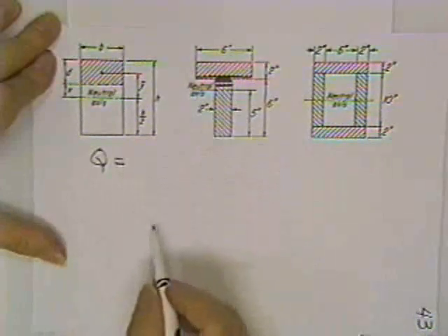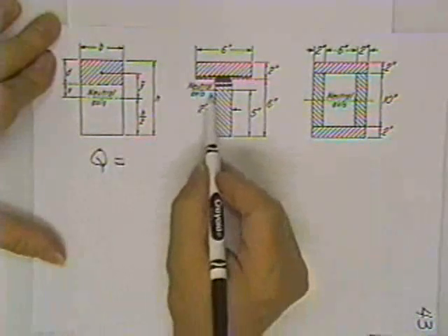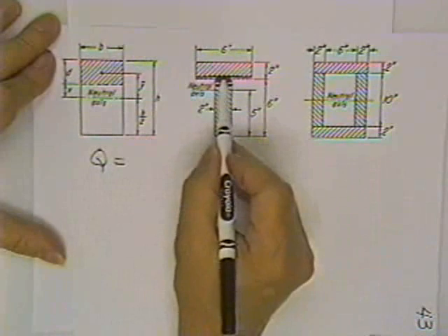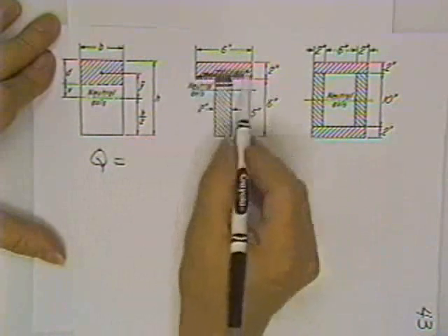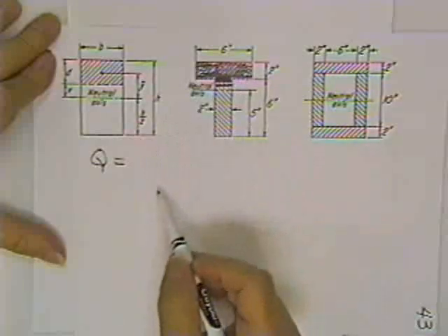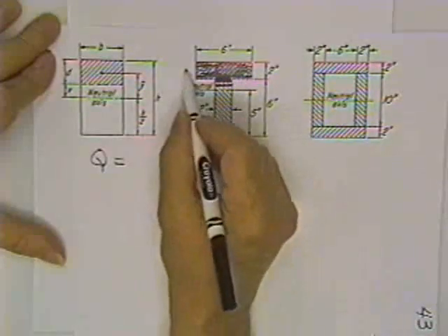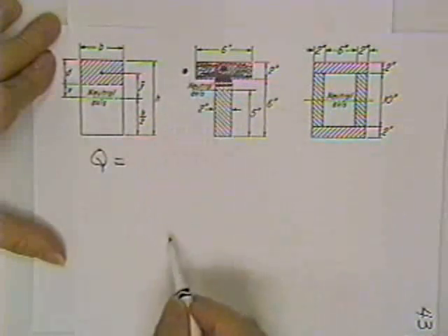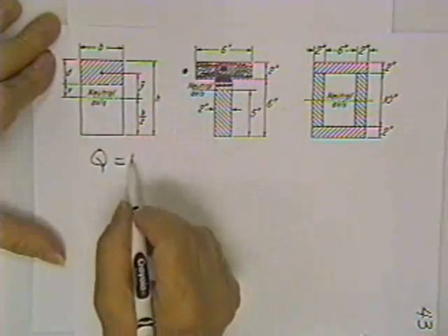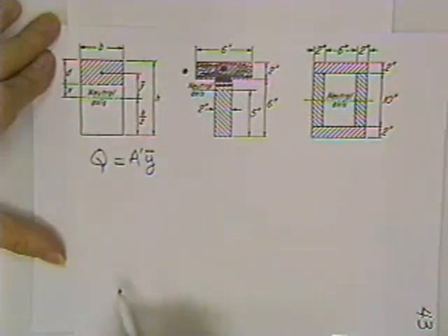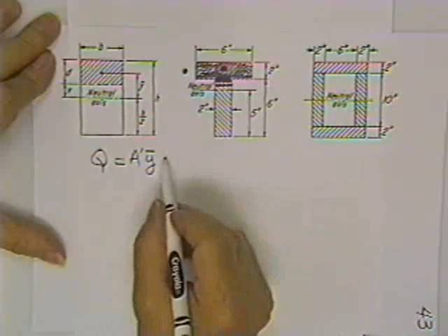Here's Q. Put my finger on the neutral axis. Go to the line where the boss wants the answer. Crosshatch everything on the outside of that line. Spot the centroid of that piece, and Q is equal to the crosshatched area times where it is with respect to the neutral axis.